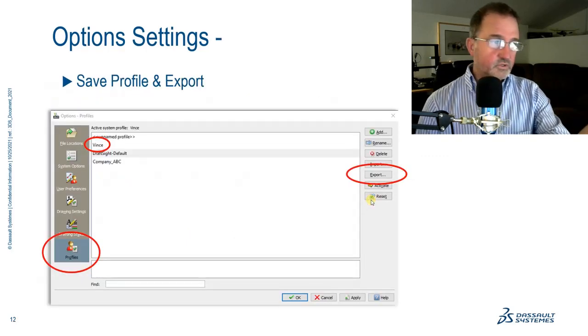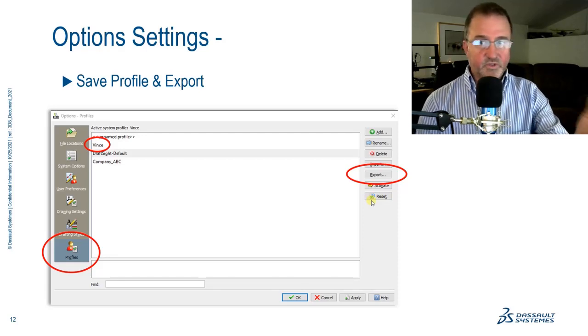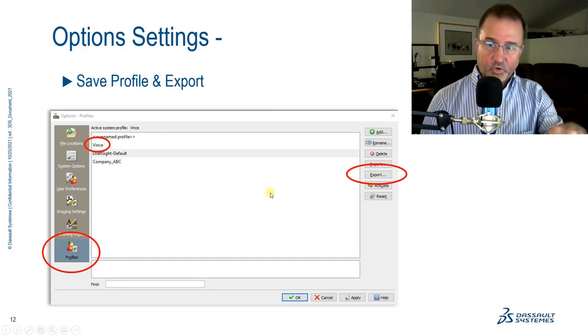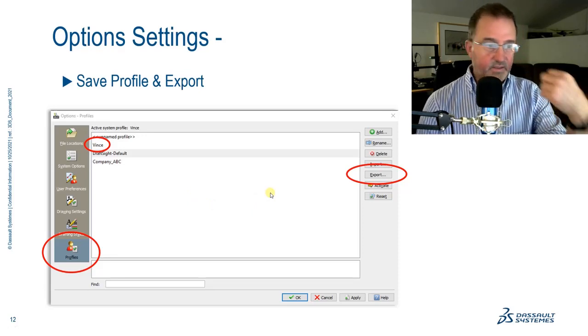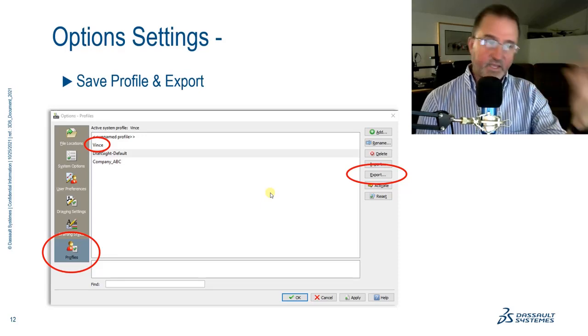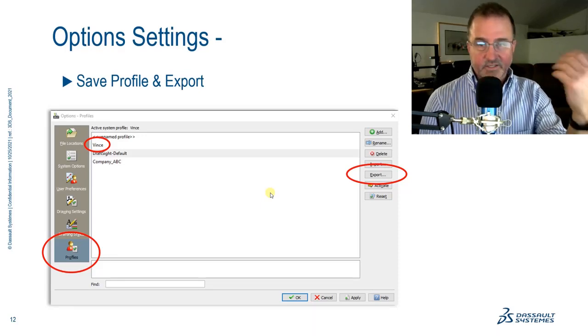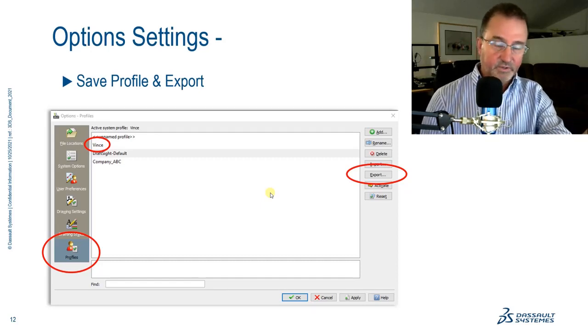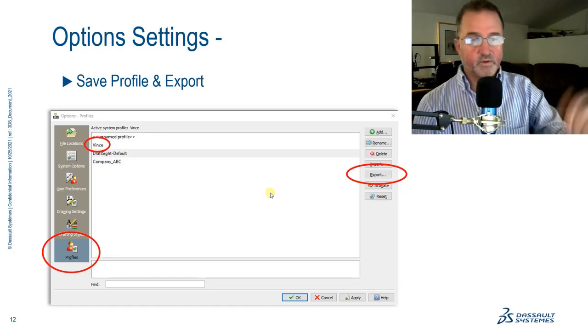And so once you've made those changes or done anything within there, the next thing I would recommend before you get even deeper is to, again, go back into your profiles on the last section of that interface and go to your current profile, make sure it's active, double check that it says that it's active, and then do an export. And the reason I say this is because as you get into more and more customization and changing things, it's always good to go back in case you do something. I like to experiment, and sometimes I wind up doing something that doesn't quite work right, and it's always good to have a fallback or to go back to a previous version where things were working perfectly fine.